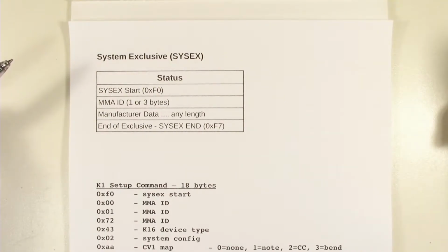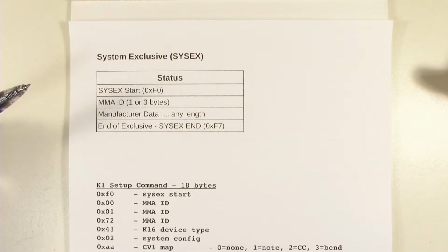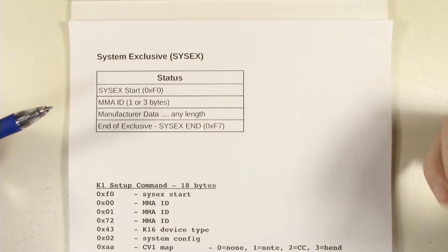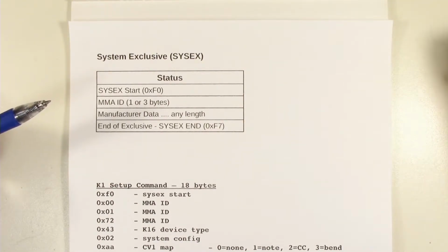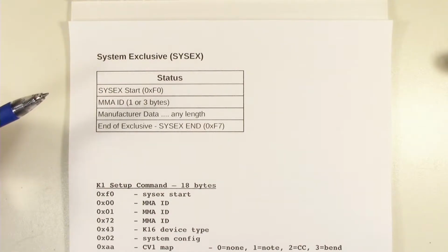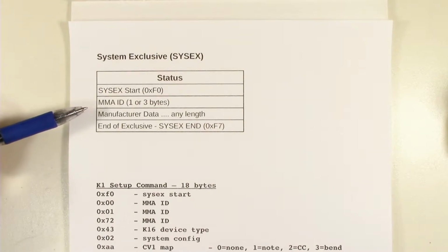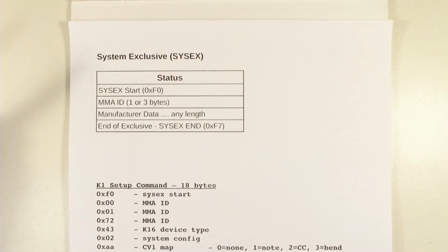A lot of devices, from a lot of manufacturers, use MIDI to update the firmware on the device. They would do that via a SYSEX message, because that means they can blast a whole bunch of data to a device, and other devices, if they happen to be connected by accident or you've got the wrong port selected, are supposed to be unaffected by that data being received, because the device doesn't have to read very many bytes into the message to realize that it doesn't care about any of the other data. It's not destined for it.